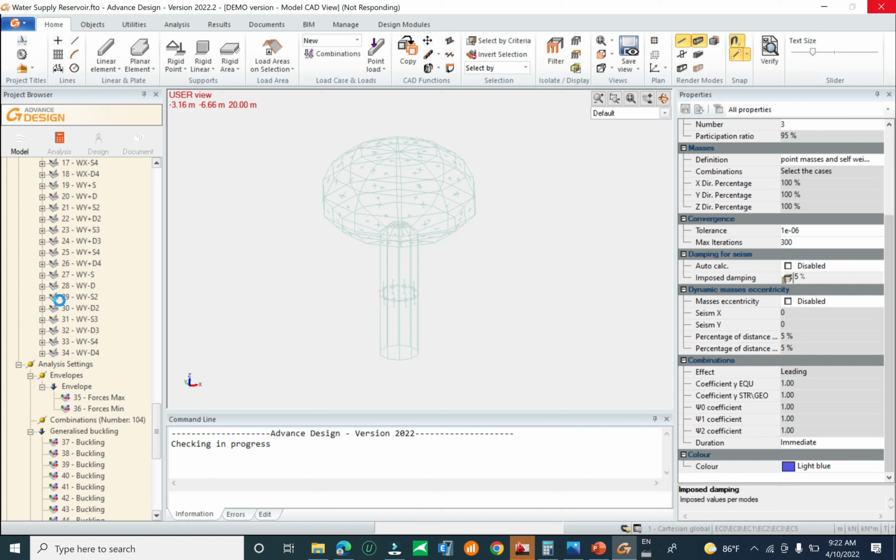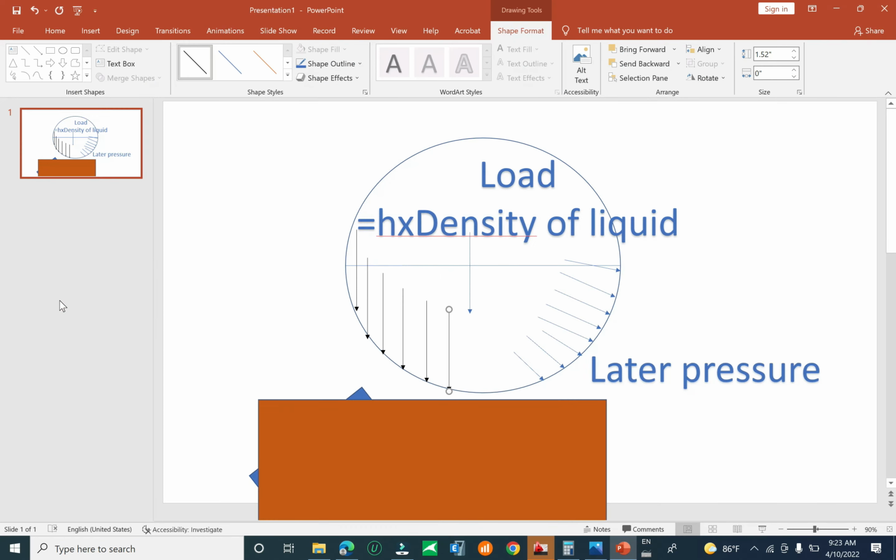You can input the load cases and load combinations manually, or you can delete some load combinations automatically output from the software and keep only the 3 or 10 that are relevant to the structure. You have to analyze which load combination is critical for your structure, so you just keep that load combination.